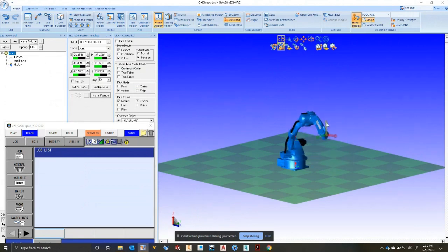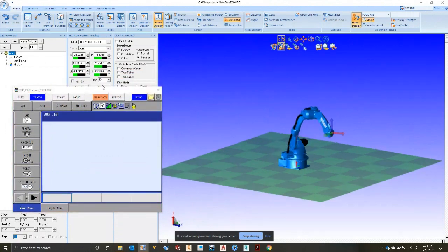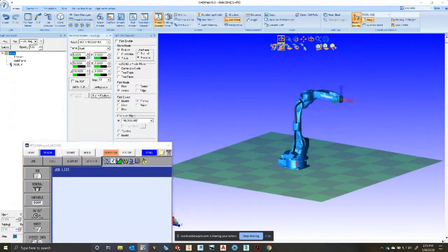This is great if you're doing some concept work, if you're in handling applications. This allows you to very quickly move the robot in different positions. So I can click, move over here, then come into the position panel, record a point. Move back, come back in here, record a point. So I can just go back and forth, back and forth. If you're getting into something precise with welding, then you gotta be a little more cautious. So let's go back to home position.